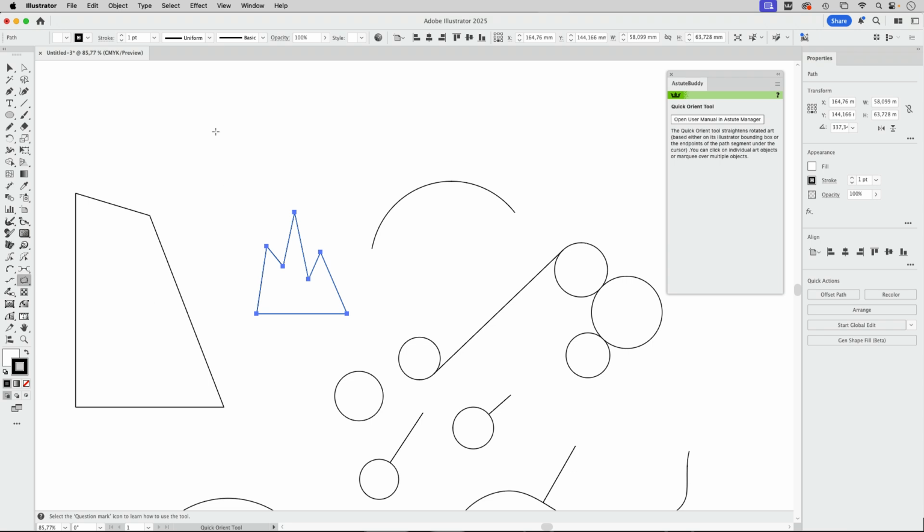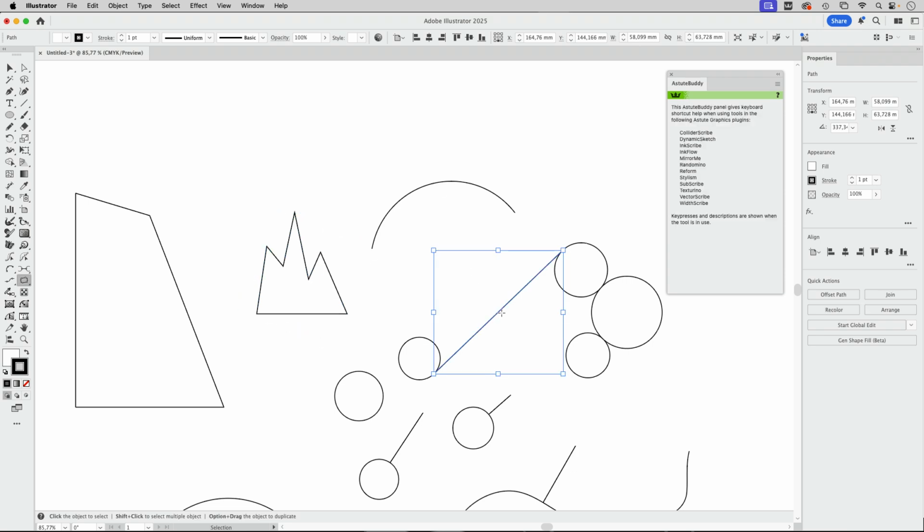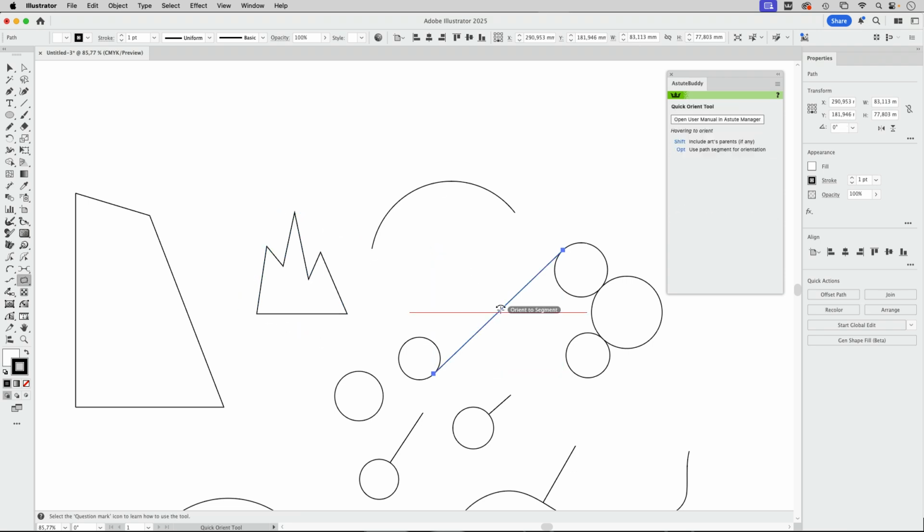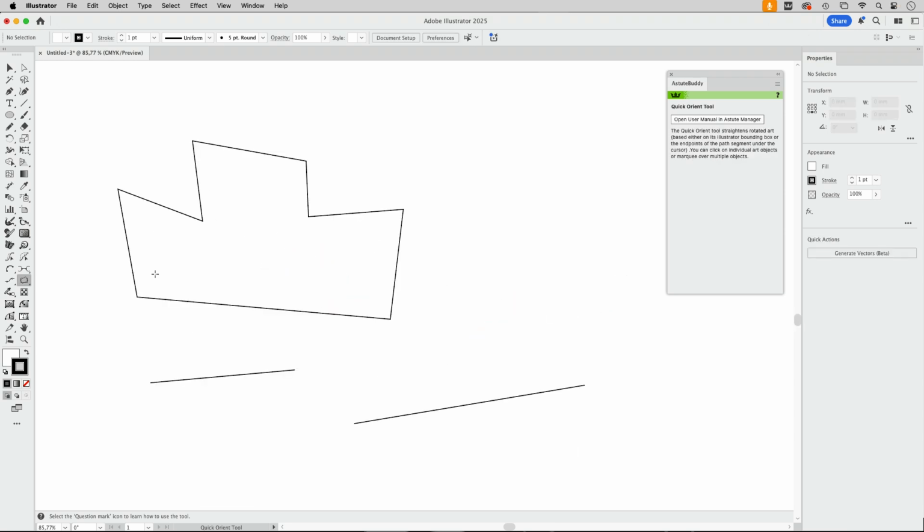So for the quick precision, let's take this one here and holding Alt, clicking just like this, and this is now a horizontal line. And then we have two more. So we've got the Connect tool here, and you can use that to connect these lines and have a nice bent connection between them.